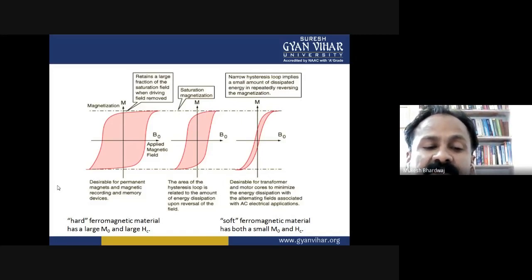The hysteresis loss is due to the form of intermolecular friction, and the term eddy current refers to the circulating electrical currents which are induced in the sheet of conducting material when it is subject to alternating magnetic field. These eddy currents produce power which is dissipated as heat. The eddy current loss, at frequencies low enough for inductive effects to be neglected, is given by a general equation.